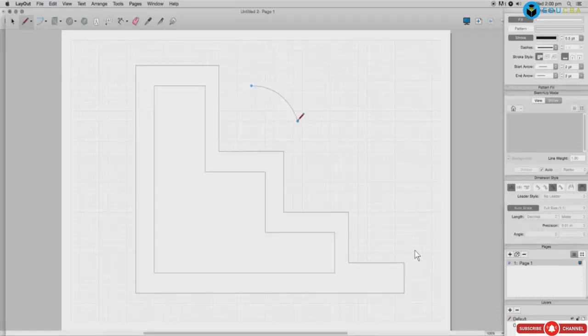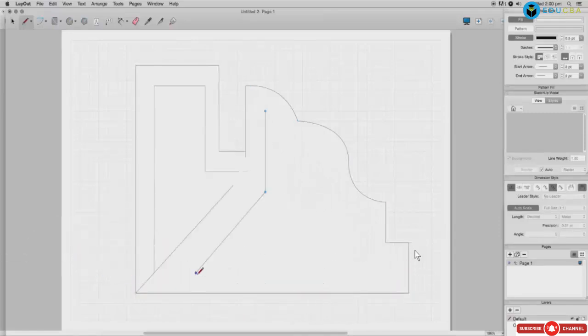And for a curve, the same tool can work as a spline tool also. Just click and drag. It can give an angle by which you can rotate your lines. Constraint angle, you can define the angle of constraint.